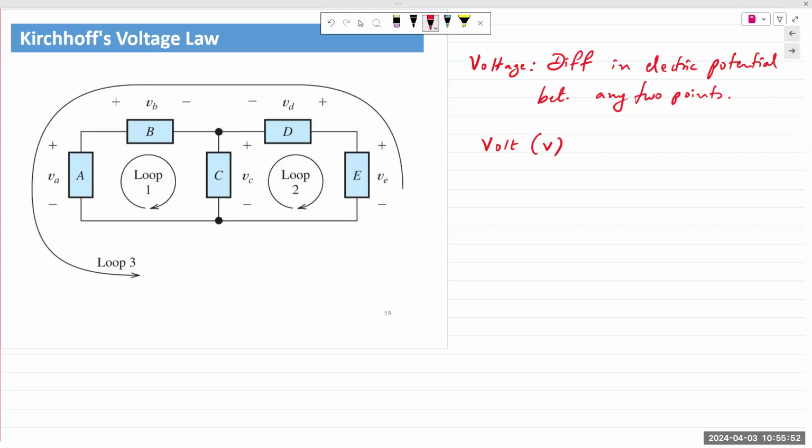Current always flows through a conductor or a pathway. So you have to actually break the circuit, insert the meter in the middle to actually measure. But voltage is measured across. So you measure between 2 points. You're directly measuring the difference between any 2 points.